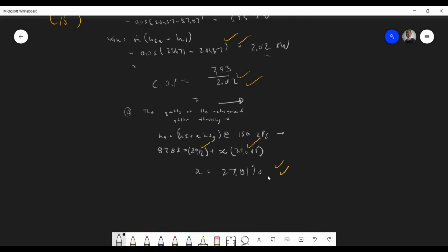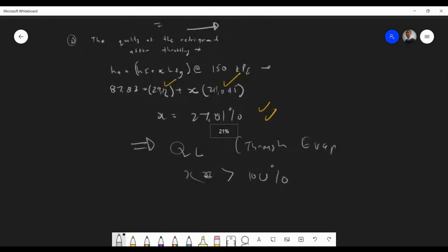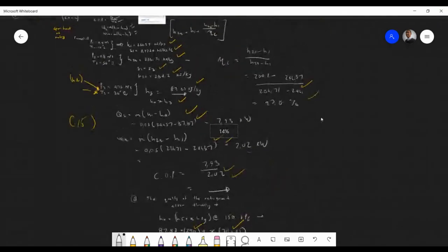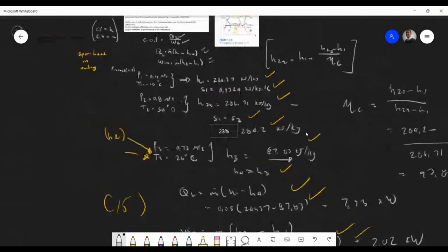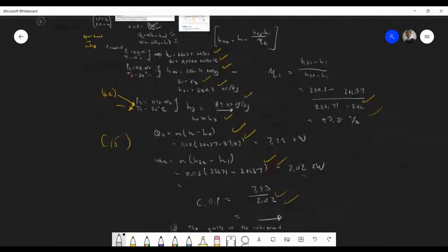So obviously then furthermore, what happens through the evaporator, this 27.81% will become in excess of 100%, which is essentially superheated, so that the compressor doesn't get any liquid. And be aware of that, I might ask these practical type questions, but I'm not opting for it. Okay. Are we all happy with this?